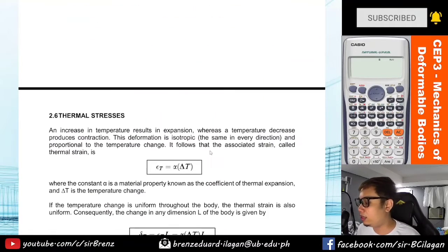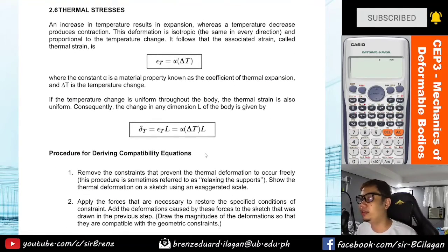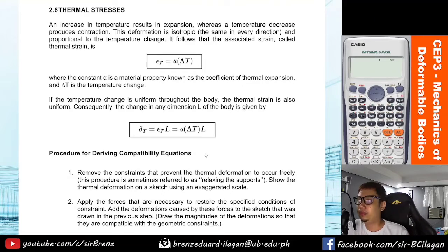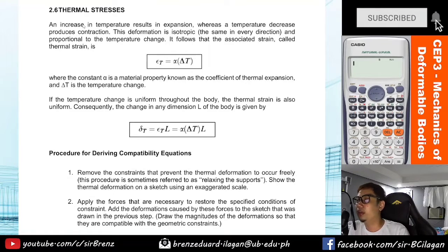Next, for thermal stresses naman. So, in thermal stresses, an increase in temperature results in expansion. Kapag uminit, nag-expand or nag-elongate. And vice versa, kapag temperature decrease, contraction or shortening. So this deformation is isotropic, meaning the same in every direction, and proportional to the temperature change.